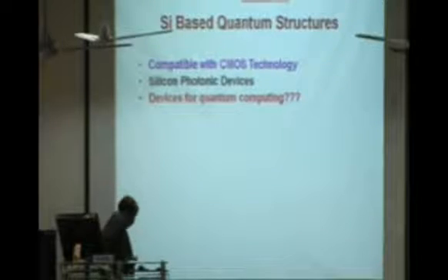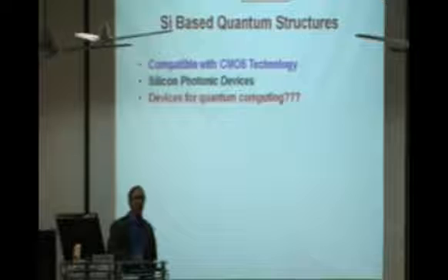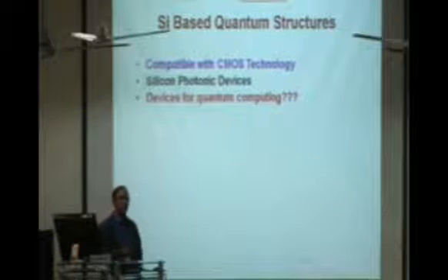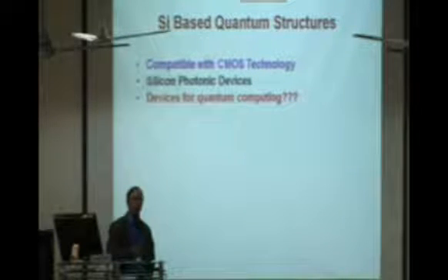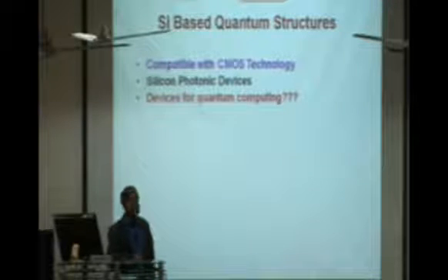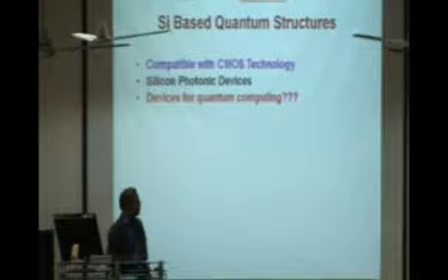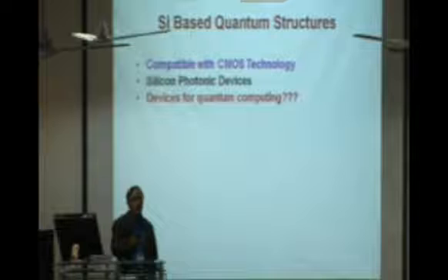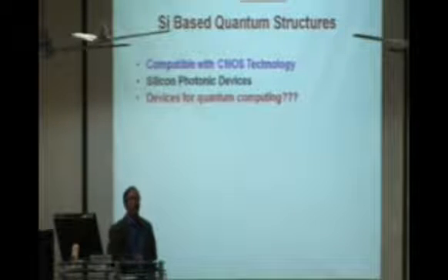The other motivation is that before quantum computing, there is another term called optical computing or photonic computing. Can you do information processing inside the chip using photons? Even that speed will be much, much higher compared to a conventional computer that you use. Unfortunately that has not yet been achieved, though it has been talked about for the last 30 years or so, because one of the problems is that you don't have a silicon laser in production or in the market, or it's not possible to make, because silicon is basically an indirect bandgap material.